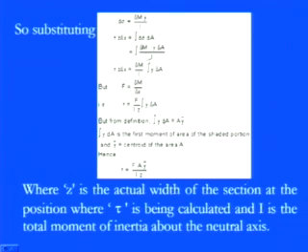So now if you consider this particular equation, then you will find that we have both of the components: we have the shear stress component, and we have the bending component, and due to that the resultant is coming. So if you analyze those things, then δM by I is simply taken out, and we have τ into z into dx equals δM by I integration of y into dA.